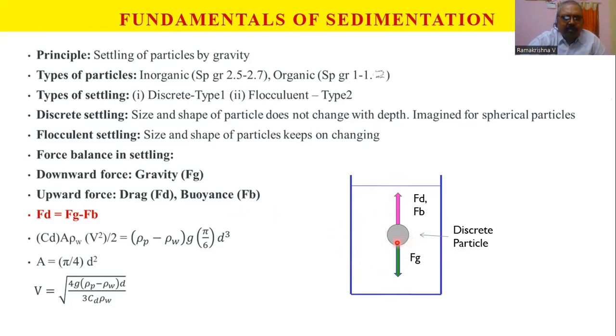Whenever we talk about settling of particles, we should concentrate on the forces acting on it. If we assume a spherical discrete particle of diameter d and surface area A in a tank under the process of settling, it will be influenced by one gravity force, the weight acting in the downward direction, and the buoyancy force in the opposite, upward direction. And because the particle is moving in a fluid in a downward direction, a drag will be there in the upward direction.